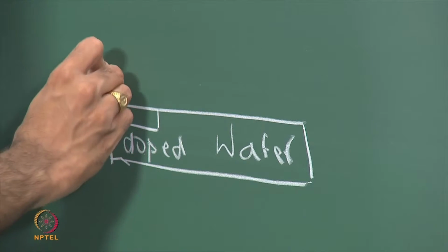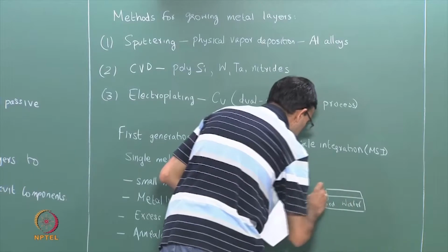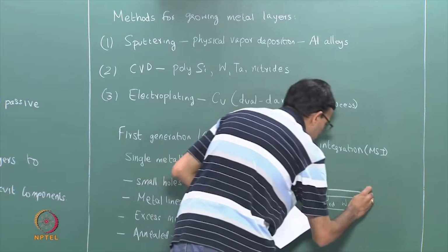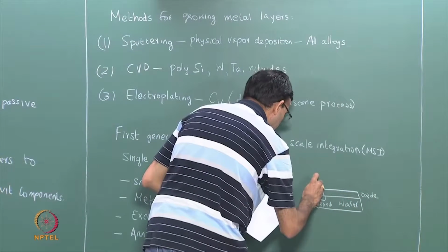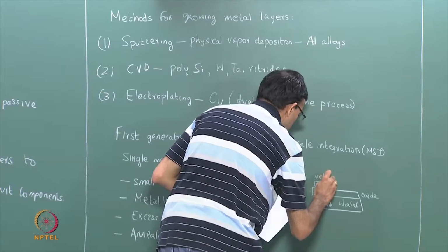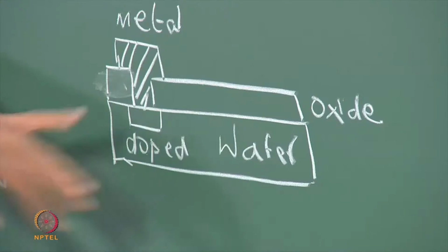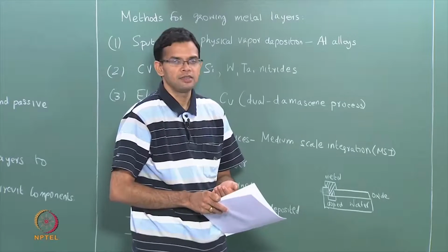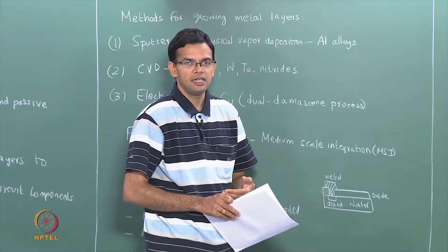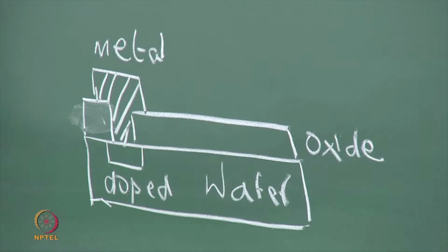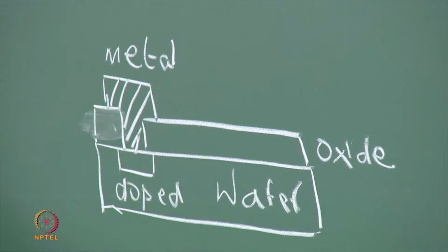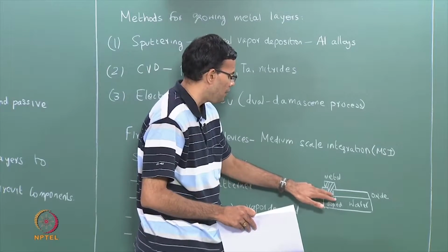So in this case you had an oxide layer and then a metal layer. So you start off with the wafer which has a doped region. There is a uniform oxide layer that acts as passivation. The oxide layer is patterned in order to open a small hole. Metal is then deposited, so you have excess metal everywhere. The remaining excess metal is then removed along with the photoresist to leave behind the metal plug, and then usually some sort of annealing is carried out to better develop the metal wafer interface.